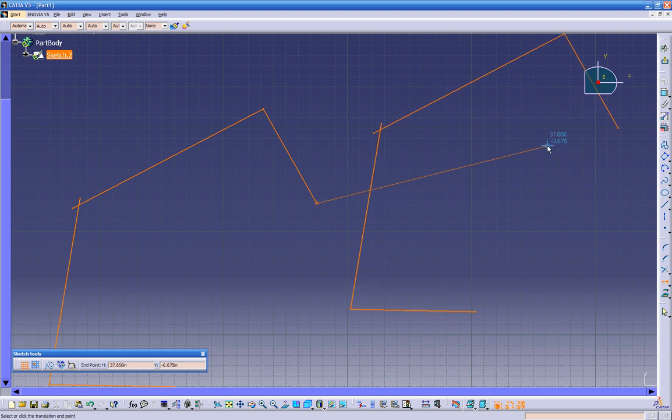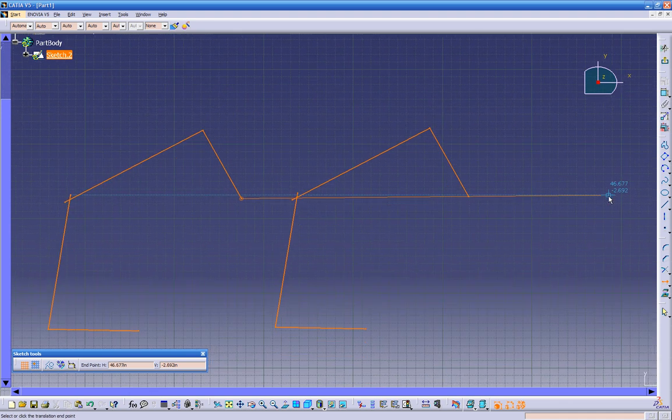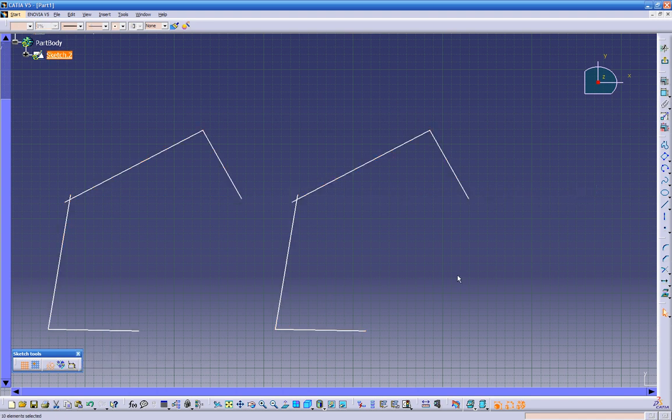While you move the part up and down, once you bring on the vertical dimension, it automatically is going to snap 10 inches apart. So right now, if you want to double check, we can click on the constraint. We can click on this point with this point, and there's our 10 inches.